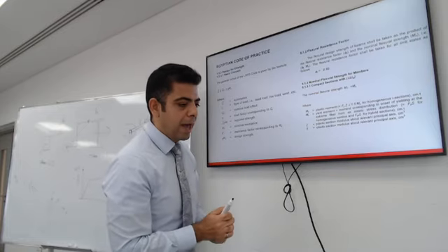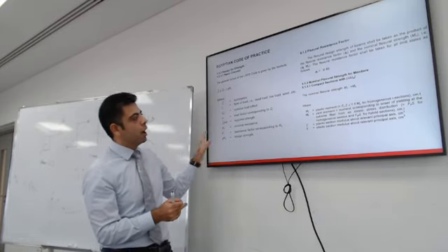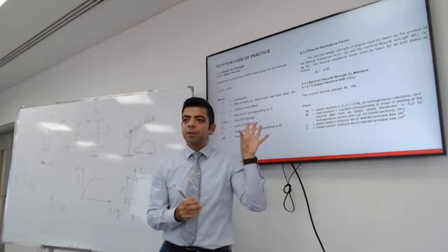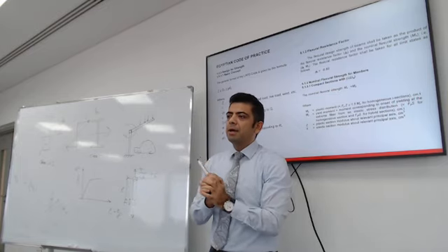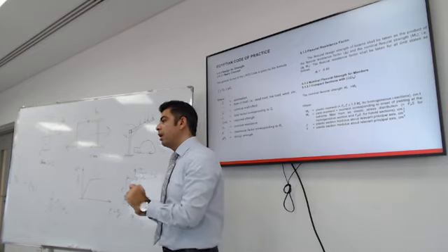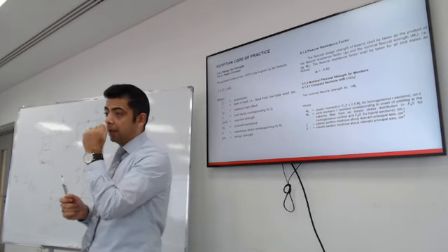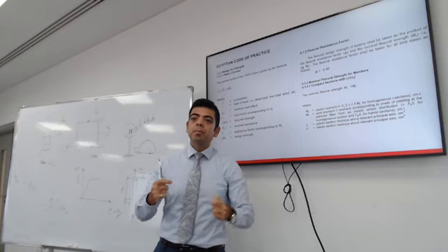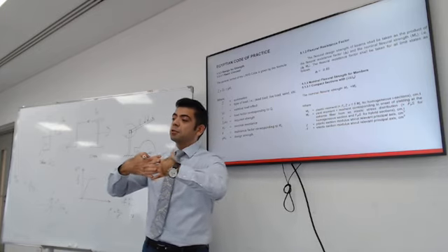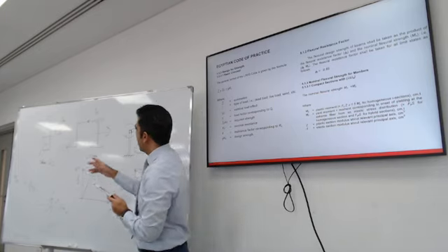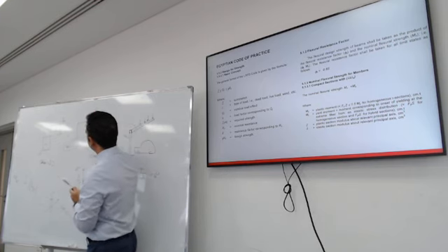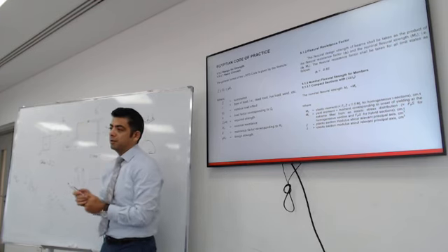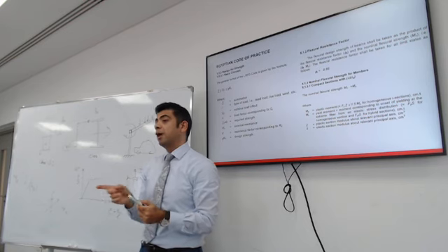So we're almost out of time. It took us a while to get through the plastic moment capacity. But before we move on, I need to explain a very important concept. Some beams, because of how they behave in the structure, will never achieve the yield capacity of the section. They will fail in a different way.